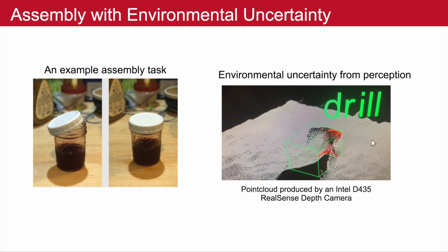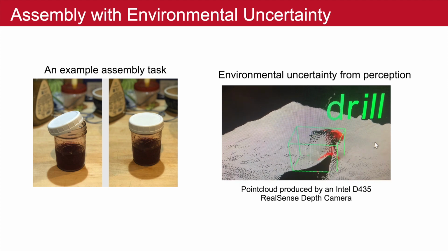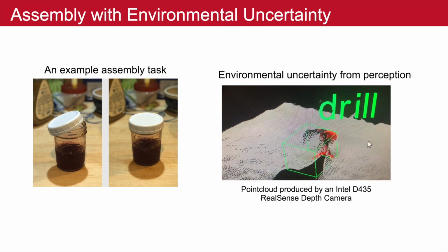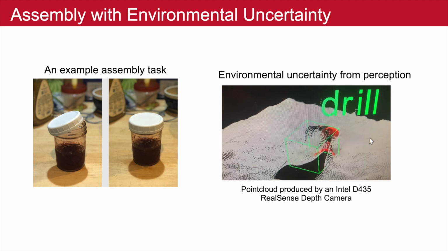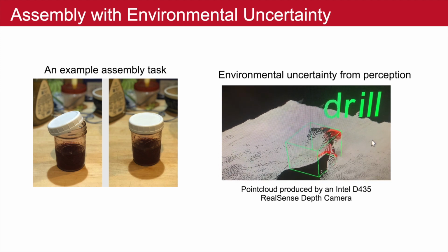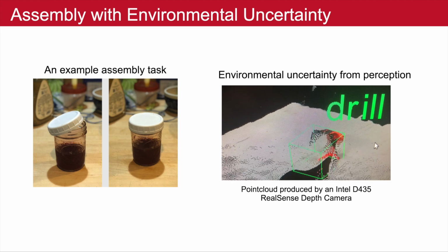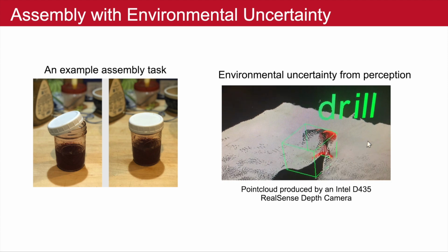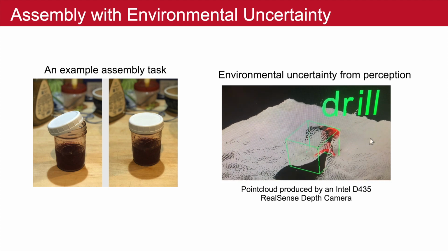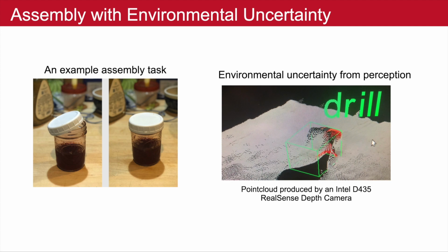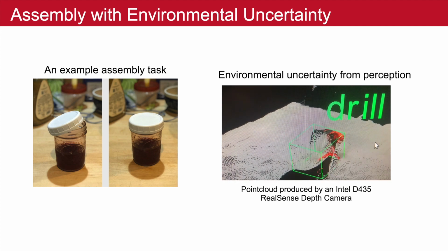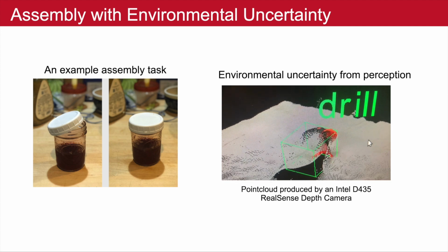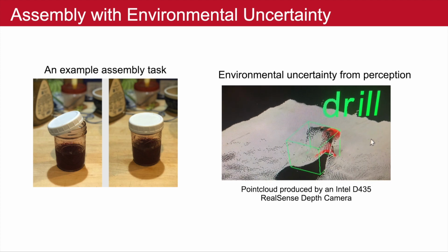However, traditional motion planners avoid all contact, which is not feasible for assembly tasks. And if, while executing a path, contact occurs, it can damage the manipulator or the environment. These planners can be modified to generate solutions that can safely handle contact, for example, by executing generated paths with impedance-based control, which better enables contact by adapting to external forces.